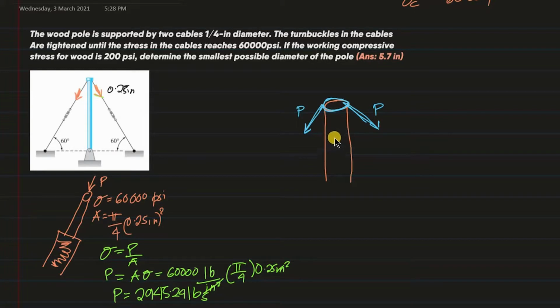Of course, hindi. Sabi natin, ang normal stress, it acts perpendicular doon sa ating area. And ito yung area natin, mga bis. So, kailangan natin kunin kung ano yung nag-act sa kanya perpendicularly. And so, para magawa yun, kunin natin yung y component ng P. Diba? Ito. Kukunin natin yung y component ng P na to because it is what is perpendicular dito sa area na to.